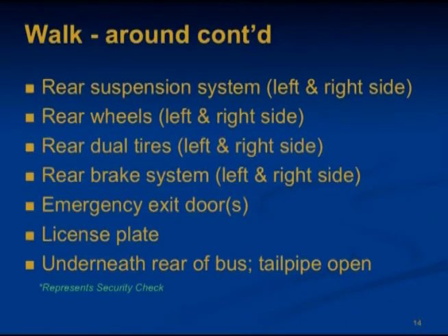The license plate, make sure that it's current and not damaged. The tag light is present and in good condition. At the rear of the bus, shine a flashlight through the emergency door and under seats to look for anything unusual. Look underneath the back of the bus for leaks and anything unusual.